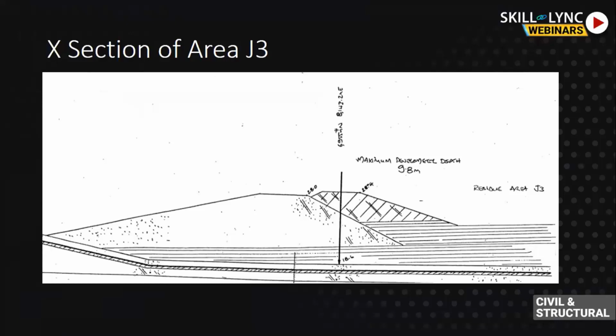The shear strength mean was somewhere around 150 kPa. The compaction practice followed in the J3 embankment was spreading the red mud by dozers and compaction by dozer track rolling. In J3, it was found that the dozer-compacted red mud has about half the in situ strength of the J1 roller-compacted red mud.